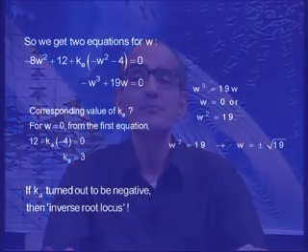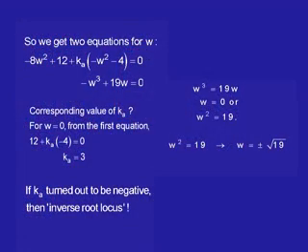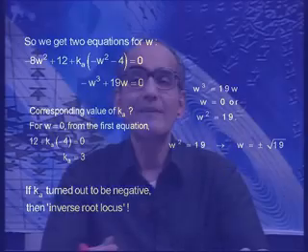Another way of doing it will look at the angle condition. That will involve, of course, calculation of or writing down expressions for some angles, and from that you can get an equation which only involves omega, but unfortunately it will not be a simple polynomial equation. Using a calculator, however, one can without too much difficulty find out at least an approximate solution for the omega value. That is the second method, but the preferred method is the one that uses the Routh algorithm or the Routh criterion.